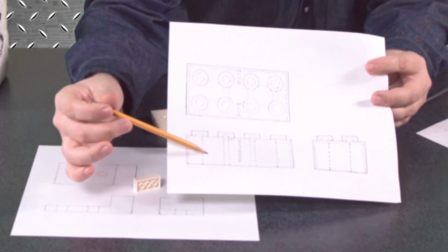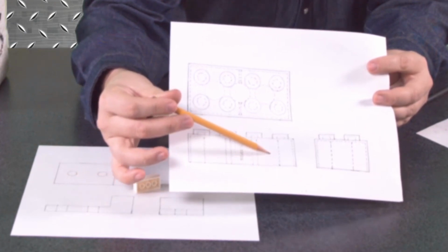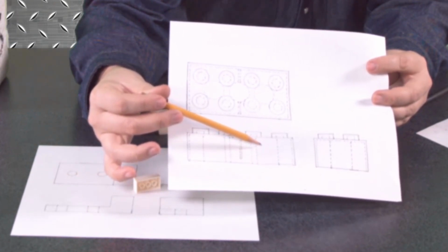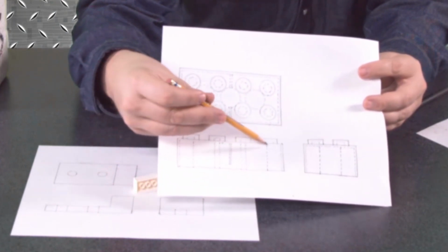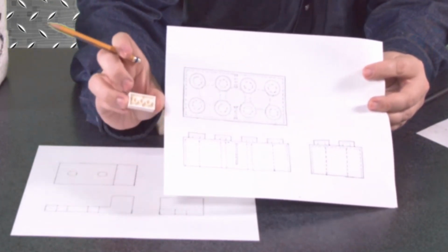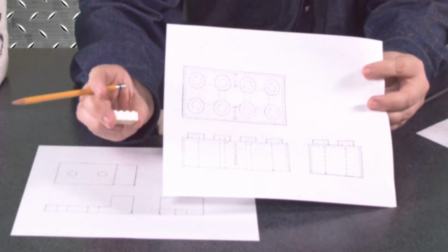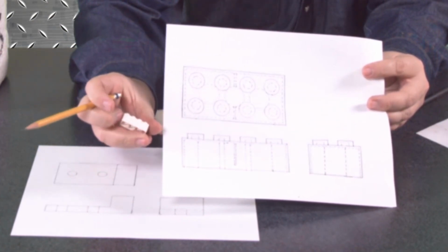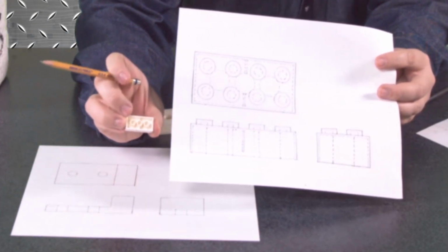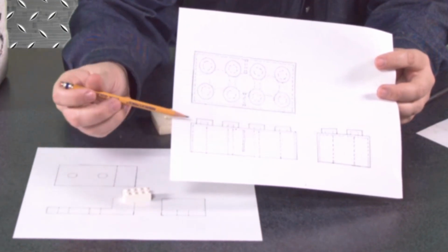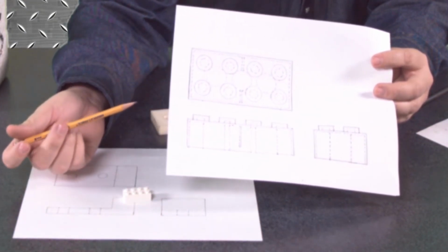So this part right here represents that cylinder on the inside. This part here represents that other cylinder on the inside as well. Now, these other hidden lines that go around the side of the square, those show you the actual thickness of the material itself on the Lego brick, because it's not just this plane and then nothing else at all. There's actual thickness to these walls. So what it's showing you is the inside edge of it. That's what those hidden lines represent.